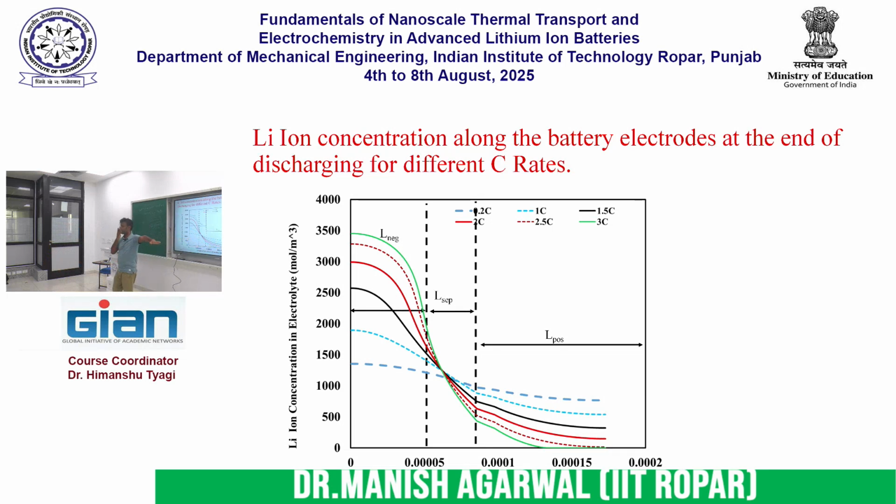Now the funny thing is, if you stop the battery, you stop drawing the current and you let it settle for some time, then what will happen? So right now voltage is almost 0, or let's say 2.2 or something. Well, it is not usable because the voltage has dropped. It is below 2 or around 2. Right? Now, if you leave this battery for some time, what will happen? The lithium ions will have some time to actually go from the anode to the cathode, right? And then the battery will recover some of its potential. Right? And again, maybe you can use it for some more time if you want to use it, right?